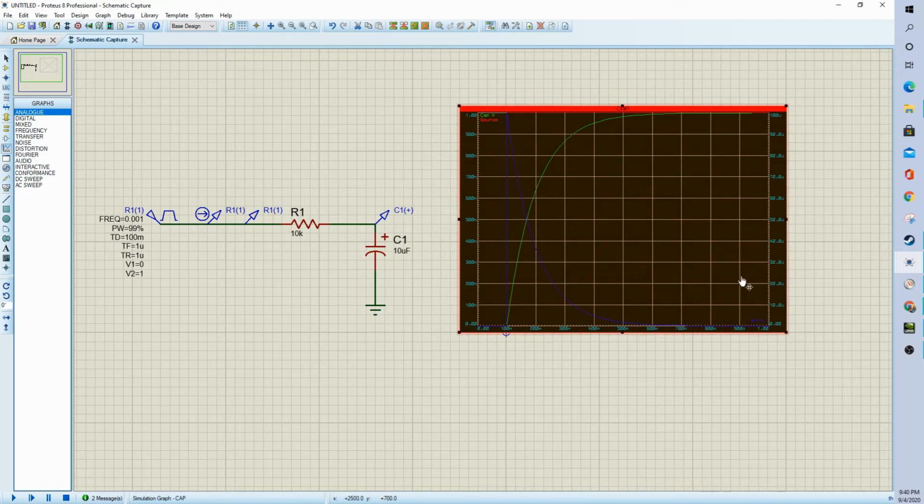Notice here that it is color coordinated. And what we have happening is our voltage at the source turns on. It's hard to see here because it exactly mirrors the current, and so our current spikes up to 100 microamps, which is basically the short circuit for the 10 kilo ohms at 5 volts. Okay, or at 1 volt, I should say.